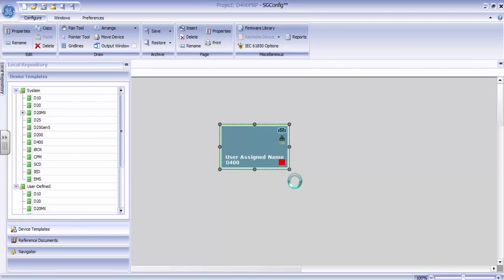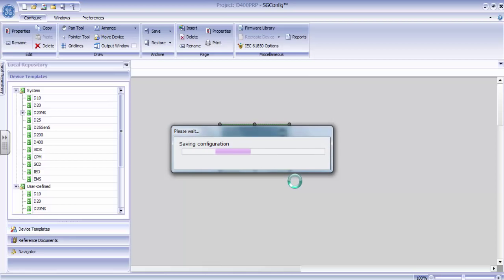So this is done. Please note that you see a red dot here. This red dot means that we recently made some changes to the configuration, and once all the settings are in place and the configuration is complete, then in the end we'll generate the configuration so that the red dot is not there anymore. However, if some error messages are generated, then this red dot would appear again. It's an indication that the configuration is not properly configured.